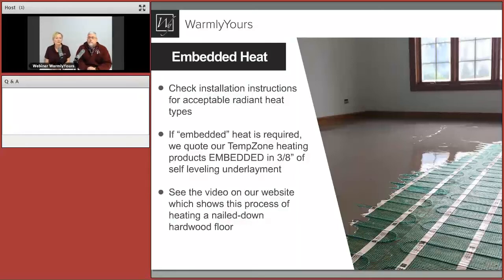Now, Larry's asking, how about a foil-based underlayment? A lot of foil-based underlayment is smoke and mirrors, because a lot of foil-based products really don't have any R value testing done on them. Some of this stuff really isn't rated for underflooring either. So if you see a radiant barrier or radiant product like that, first of all, there usually isn't a real R value associated with it, and all of them that I've seen haven't been rated to be underflooring. So it's very important that when you see that, make sure it's rated as an underfloor, a subfloor product.